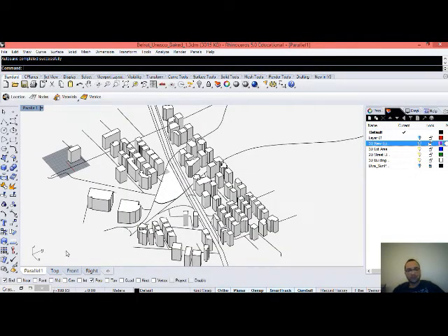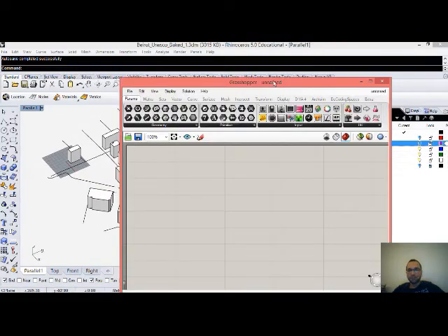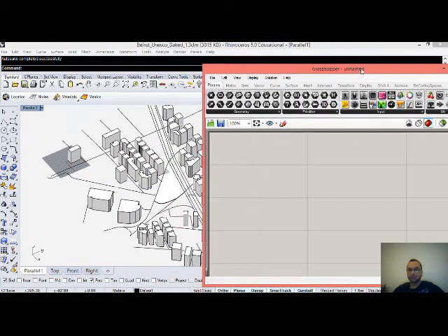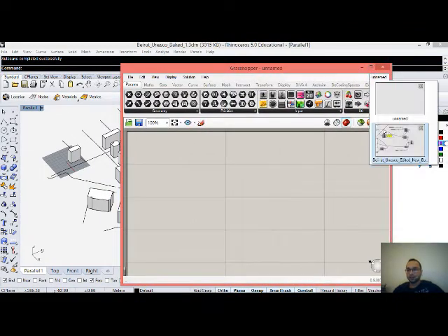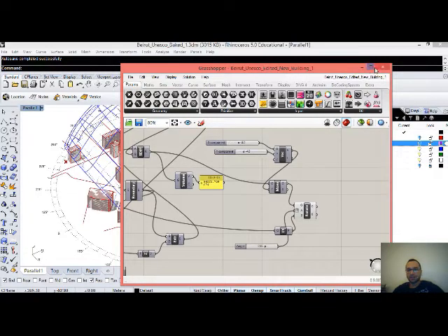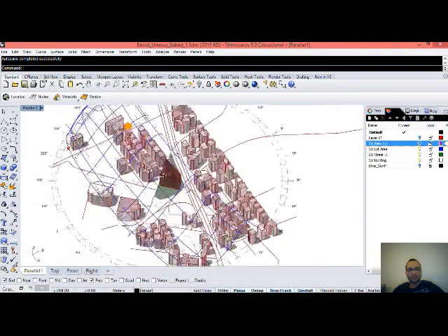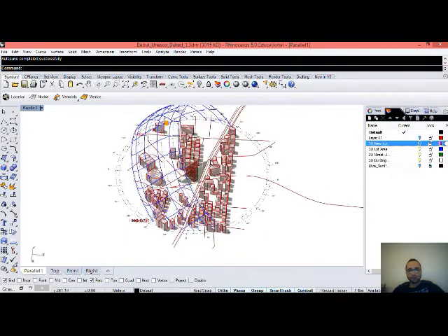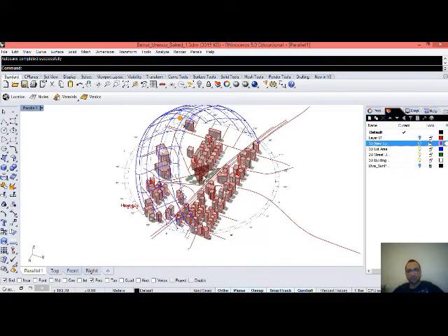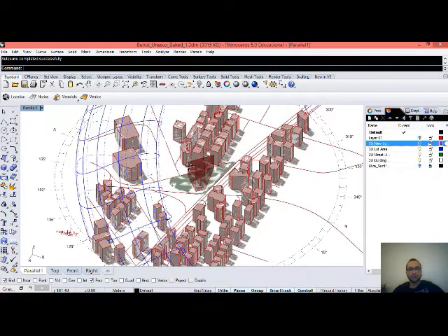Using Rhino and Grasshopper, I developed the 3D model of the site. And as you know, Grasshopper is a parametric tool that allows to display the 3D sun path regarding a specific location with shadow analysis in real time.